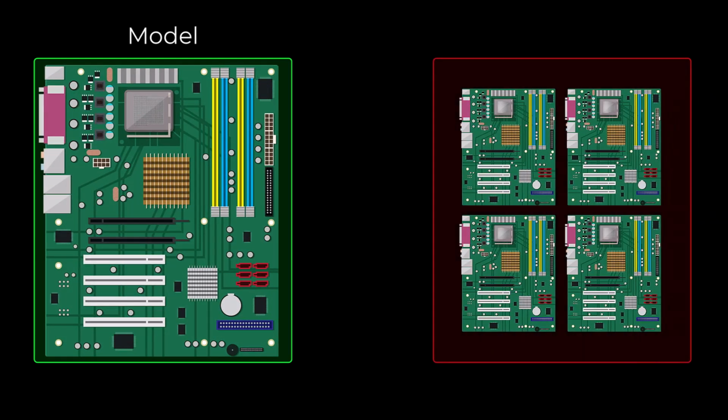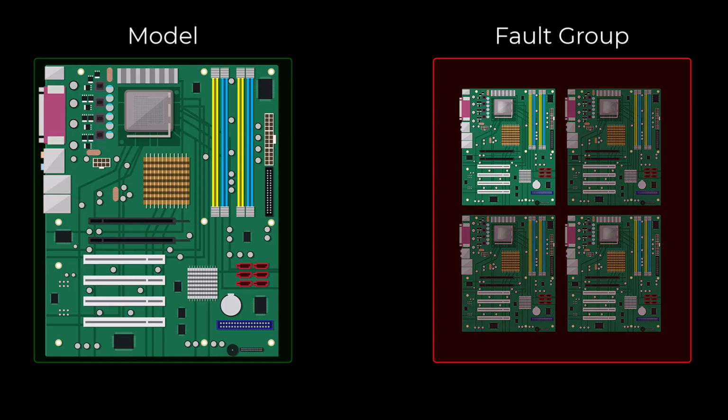To create the model that defines how non-defective devices should behave, one or more operational devices are tested under power. At the end of each test, the sequence of images captured during the test are automatically saved with a unique ID. The model is then created by combining these operational device tests into one model sequence with specified pixel limits. Defective devices that have been successfully troubleshooted are added to the fault group along with failure mode and repair details.